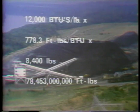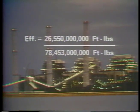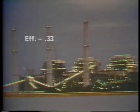Now we go back to our efficiency equation and put the numbers in. Well, we had the energy out equal to 26,550,000,000 foot-pounds. And we just calculated the energy in as 78,453,000,000 foot-pounds. Dividing the two gives us about 0.33. If we multiply this by 100, we get percentage, which is about 33%. In other words, only about a third of the energy in the coal is actually converted to electrical energy.